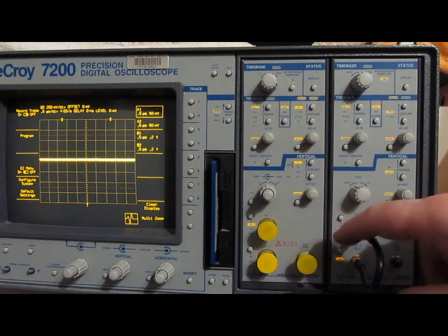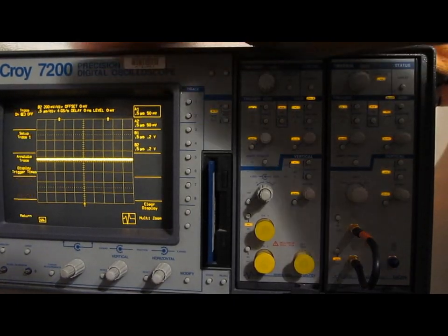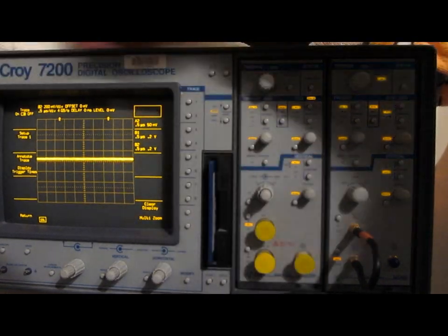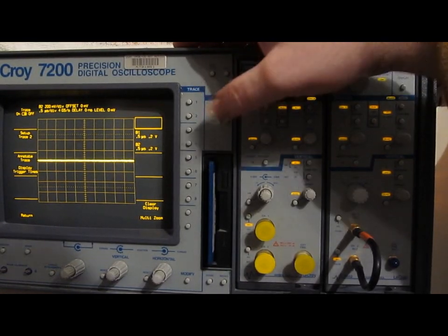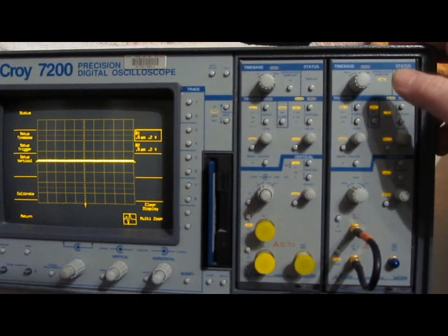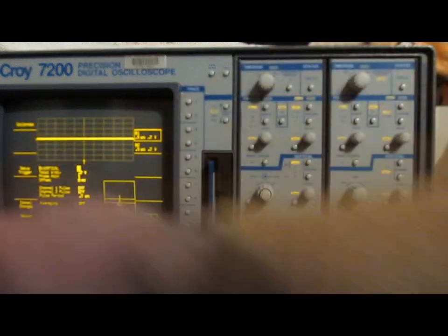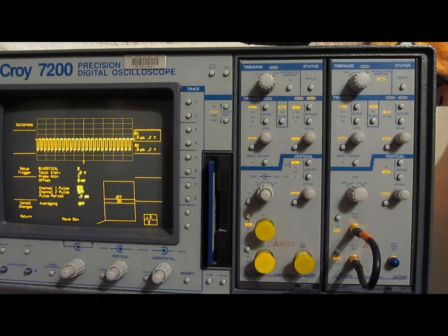Okay, we're going to start with just a jumper between channel 1 and 2. What I'll do is go ahead and turn off the A plugins channel 1 and channel 2 as well. And then for B1 channel 1, we'll select display and then vertical setup. And then down here we can select pulse. And you can see it's now putting out a square wave.